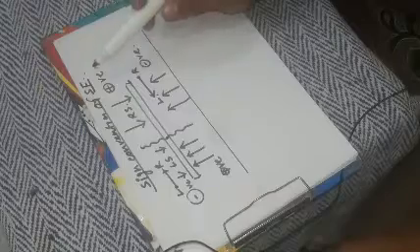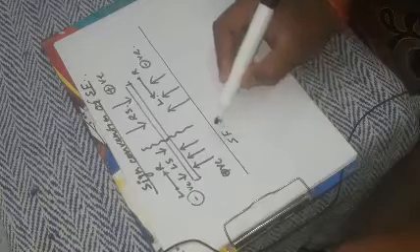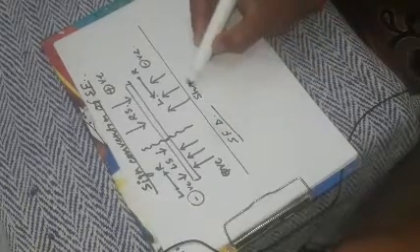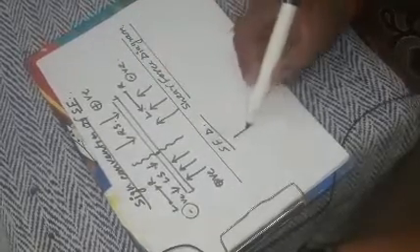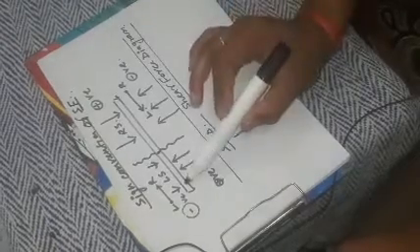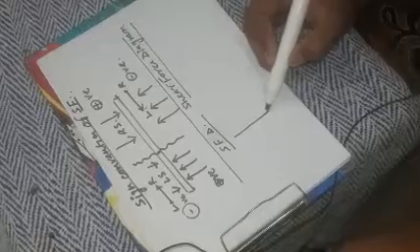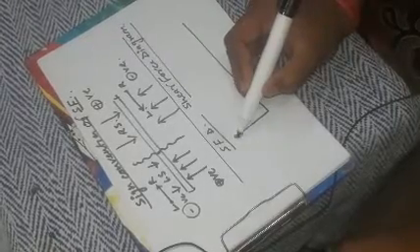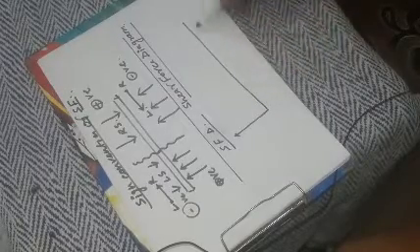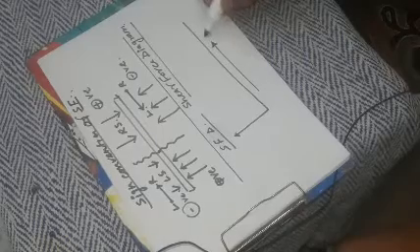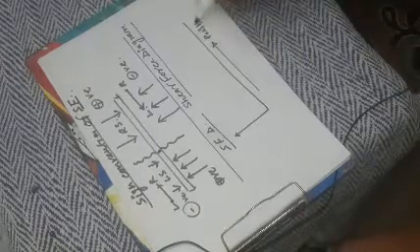This is all about the sign convention for shear force. Now let's discuss the shear force diagram. In case of a shear force diagram, the value of shear force for each point will be denoted on the ordinate and the position of cross sections will be mentioned on the abscissa.